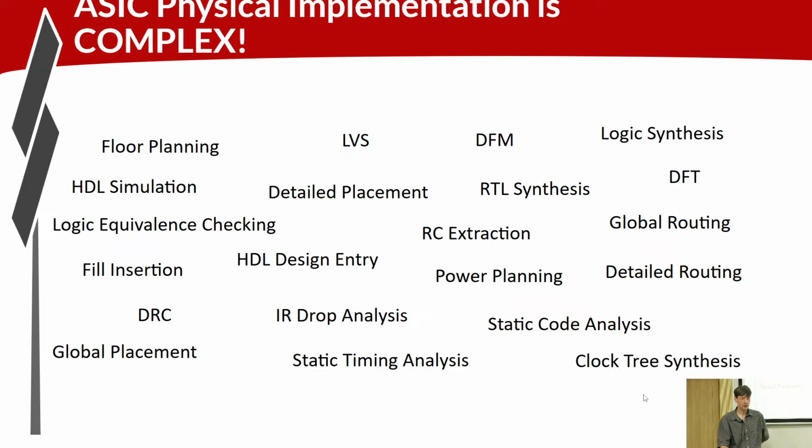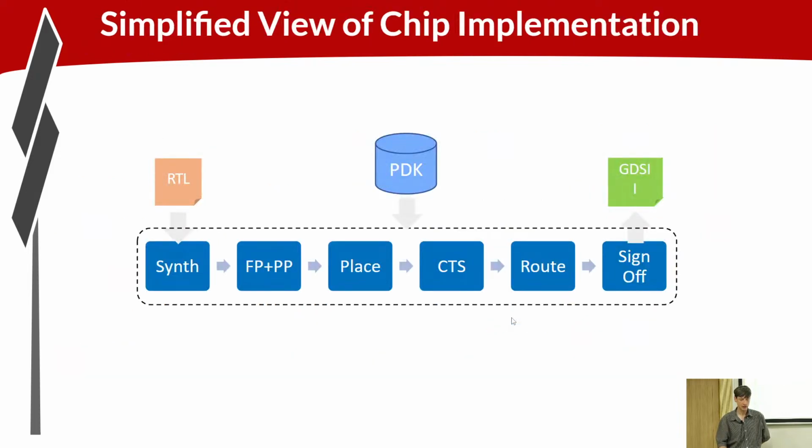Okay, a lot of stuff involved in physically implementing the RTL that you write. So a lot of different tools. We'll take a look at the big picture of how these work. First of all, I'm not the best person to go over these slides, but at least at this level I can explain these different steps. My focus is all RTL and above, ones and zeros. Here we're looking below that. So your RTL goes through logic synthesis to become the gates that define your functionality.